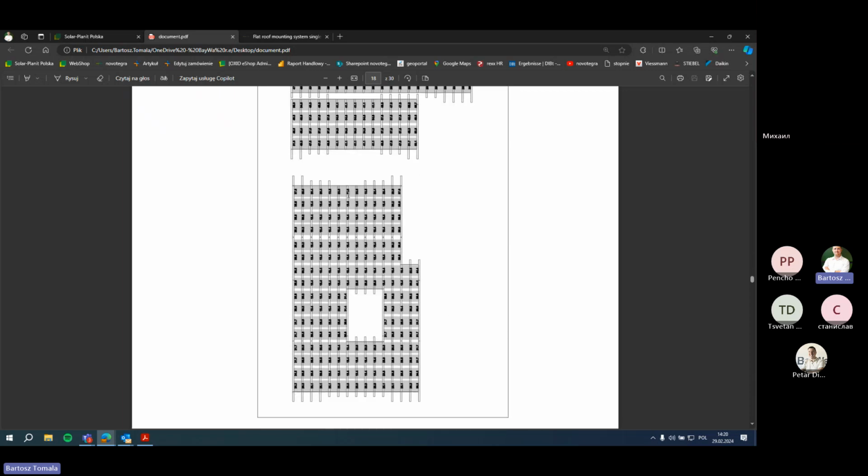Or also, if it is still above this maximum roof load, we can make this construction hybrid, for example, by using some plates welded to the roof covering and connecting them with the construction to put the ballast below the value which was the maximum.